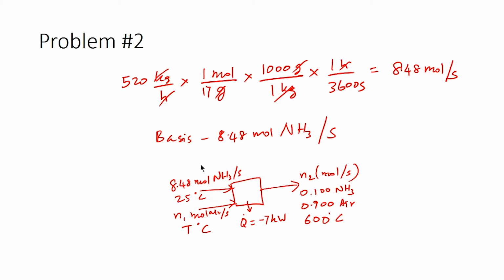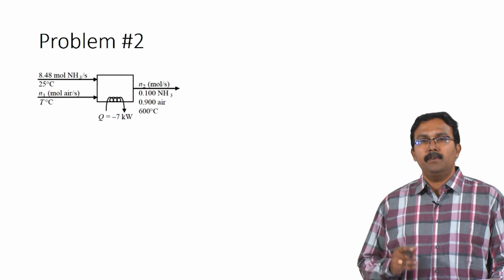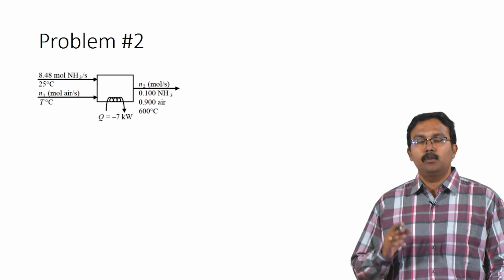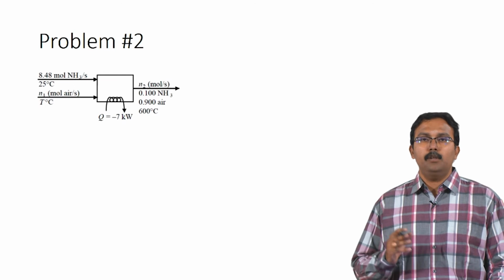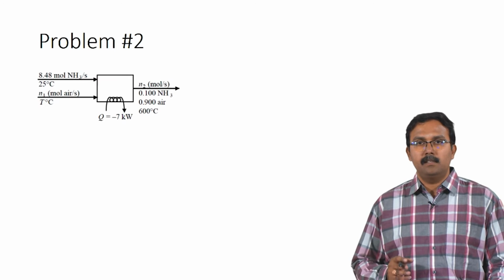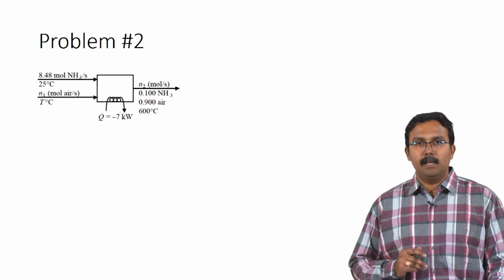So, now that we have this flow chart, we need to first perform material balances to get some of the values which have to be calculated. We will see whether material balances by themselves are sufficient, and then we will proceed further. To identify if material balances are sufficient to get the flow rates, we need to perform a simple degree of freedom analysis using only the material balances.